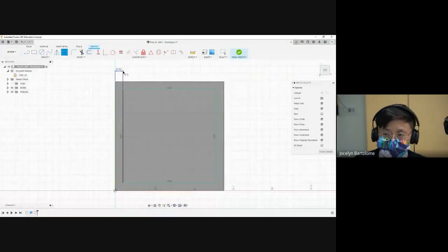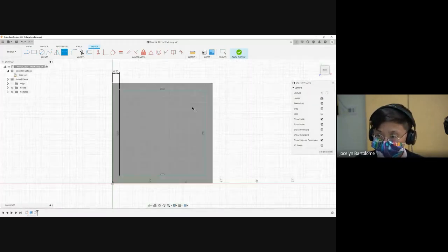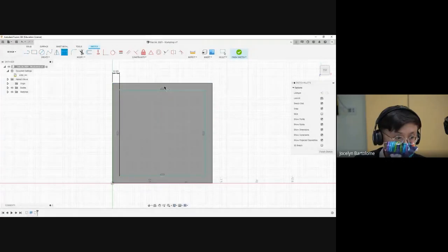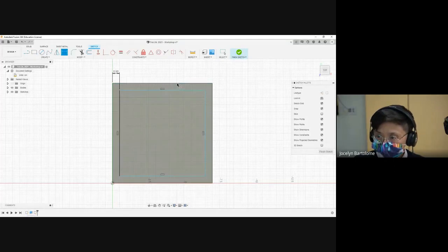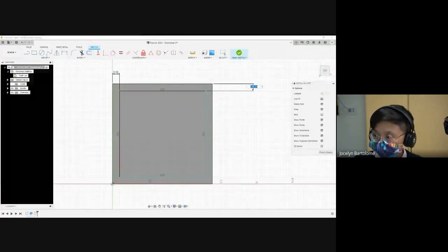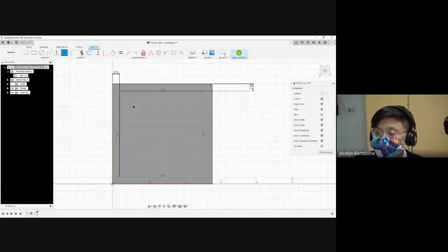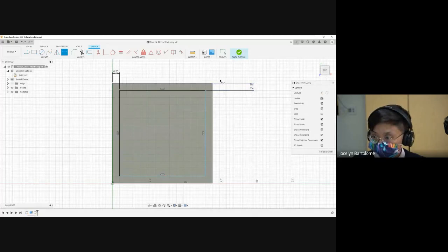As you can see, I don't really need to specify what my units are because we already chose our default units to be centimeters at the beginning of this modeling tutorial. We're going to do a similar thing with another edge of our box and square. So I'm just going to choose this top line over here and the corresponding line of our box. Click twice. You're prompted to click one more time and then enter 0.5. So now our inner square is perfectly centered with respect to the edges of the outer box.